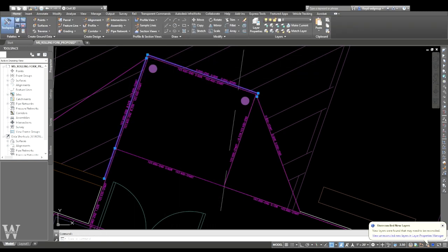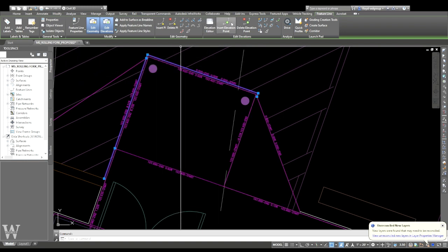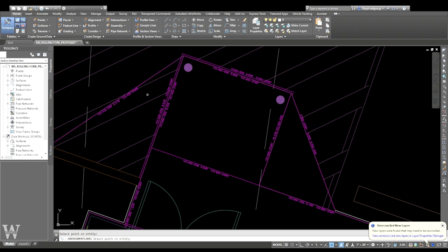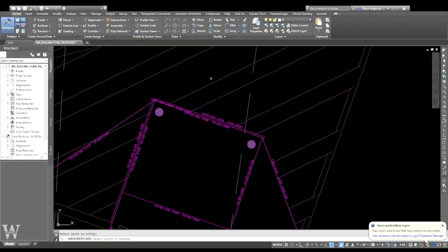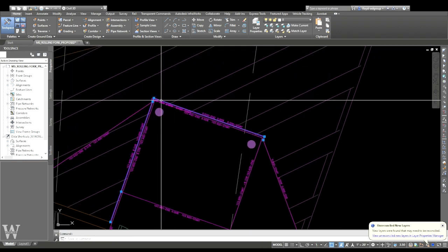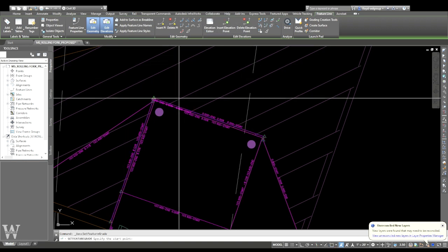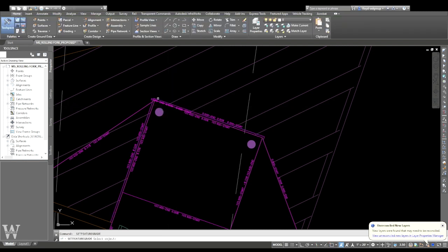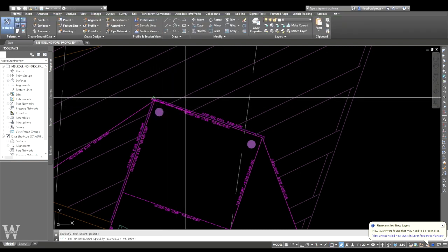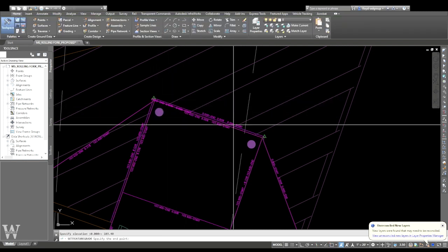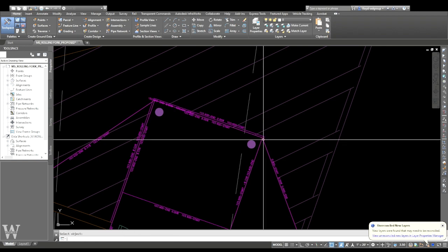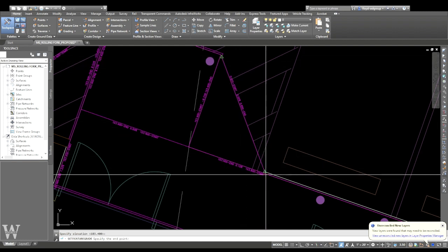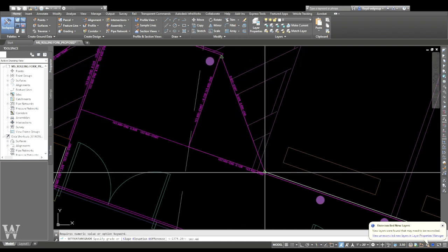Okay, so we labeled to that point, right? Because we'll check this one right here. It's got elevation on both ends. So we'll highlight right here, and we'll go from here. We actually can go all the way to there. Whoops. We better tell it what we want it to go to, right? 103.40. And you can go all the way to here at a 0 grade. And then we pick it up from here to here at 103.40.